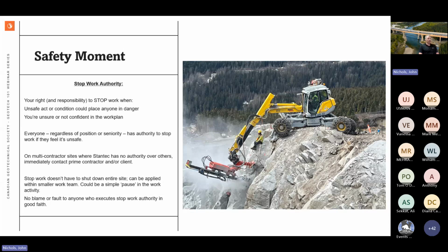Before we get started, I think it's important to do a safety moment. You can see from this photo taken on a project a few years ago, if you can't see the hazard now, then look a little harder. There's a rope access technician sitting on a spot that's being spot bolted, and essentially he's not paying much attention to what's going on overhead. We know this is an unstable slope, and it's pretty typical to be next to a bolting pattern like that, but he should be off to the side. He should be focused on the work being performed.